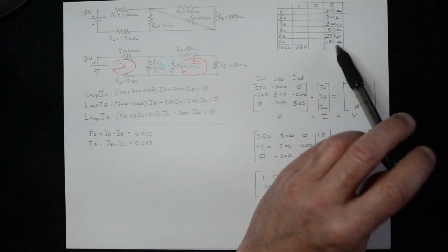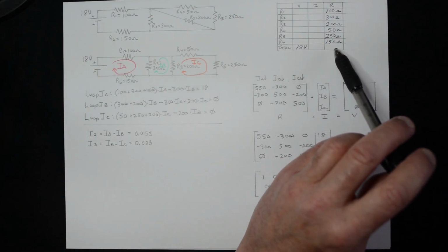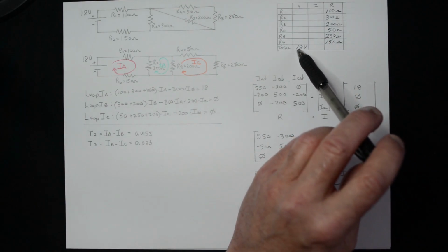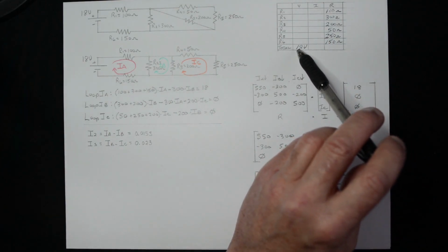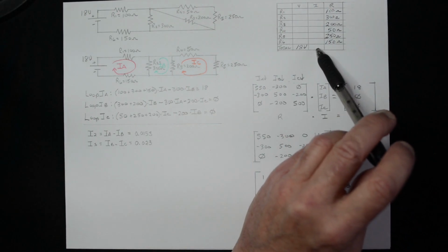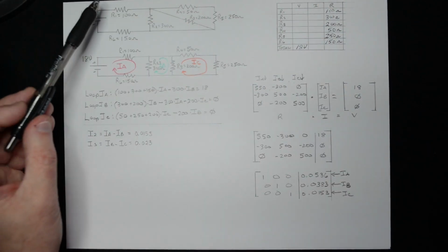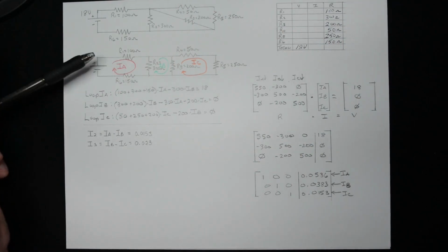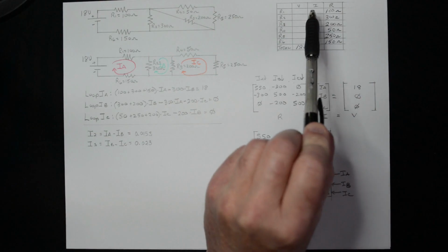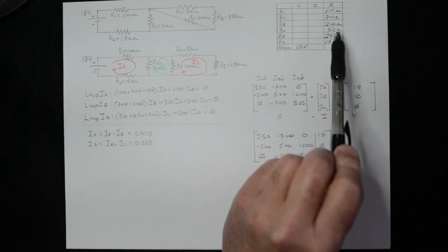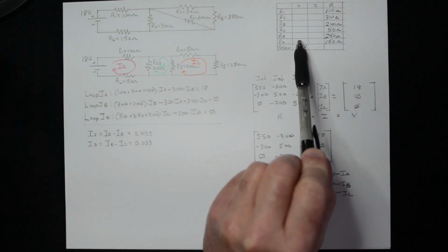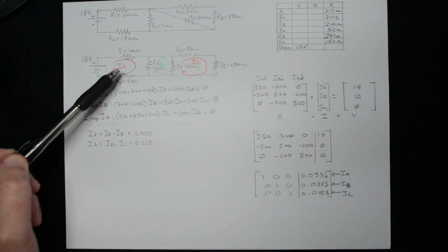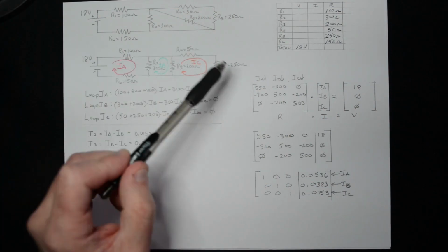But in this case, you know you would just find RT, total resistance. And once you've got that, then you can calculate current because you have the circuit source voltage, 18 volts in this case. And once you have the current, you have to look back at the circuit. This is IT, total current, and recognize that I1 and I6 are going to be the same as IT. So then you calculate the voltages off of that. So you have V1, V6, and you recognize that VT minus V1 minus V6 is the voltage left over for the rest of the circuit.